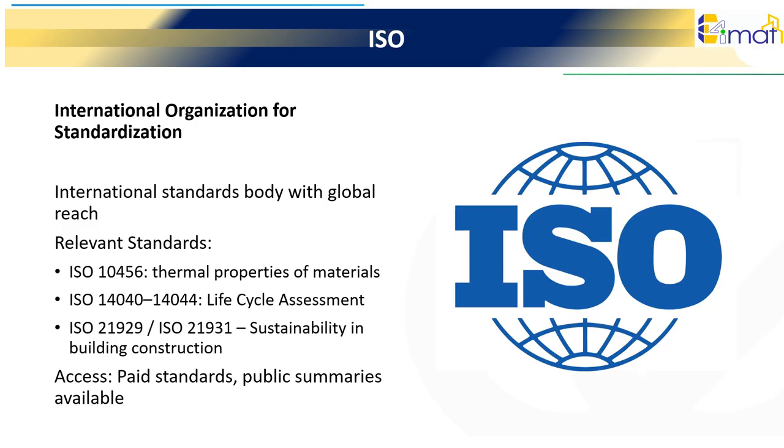ISO, the International Organization for Standardization, is the main global developer creating harmonized standards across countries and industries, including construction, materials and sustainability. For our topic, ISO 10456 provides reference thermal properties for building materials, ISO 21929 and ISO 21931 address sustainability in building construction, and the ISO 14040 series outlines life cycle assessment methodology.